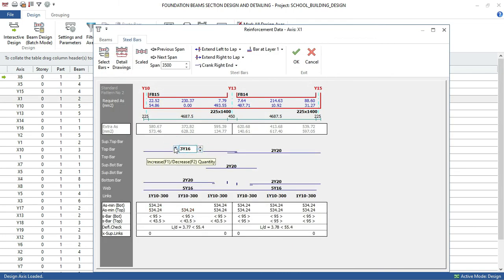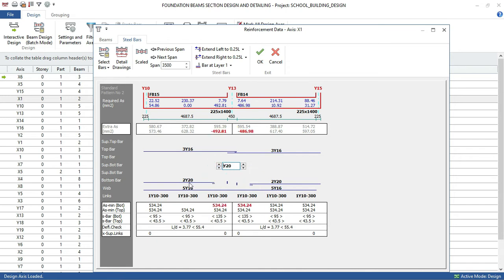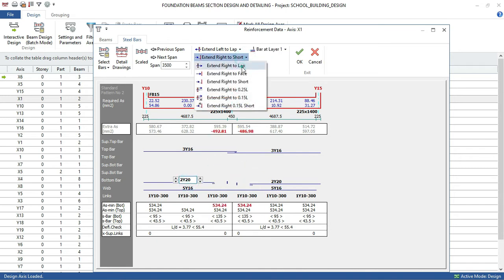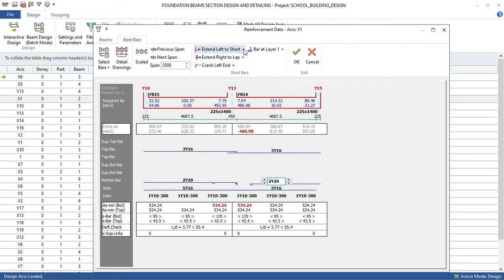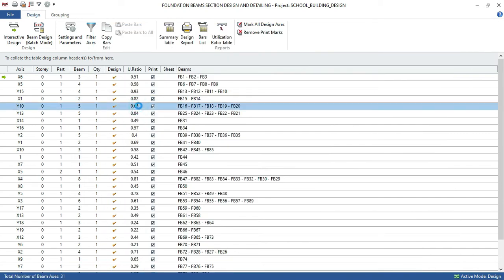And if I continue doing it, it will look boring because you will see that it is the same thing which I'm doing just now. So the whole idea is for you to check the beams and do just what I'm doing just now. Reduce the size and then increase the number once it's failing. Now, once you reduce the size, there will be a failure. This thing here means failure, here means failure. So you have to now increase the bar number for you to be able to pass, and then it is okay with this. So you can go here right now, click on OK, and then go. Let me just go again.